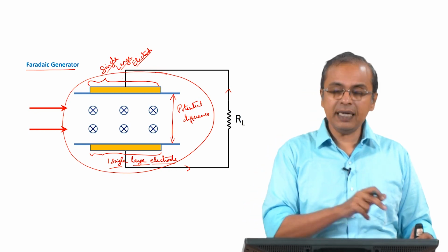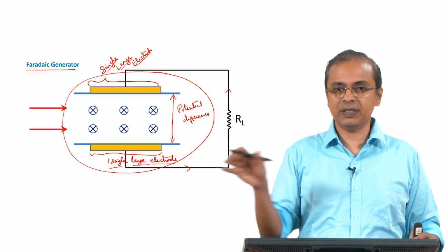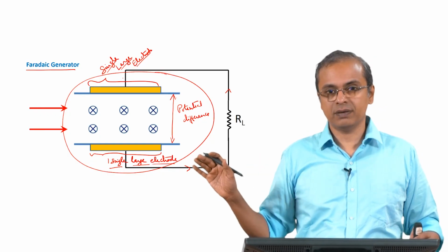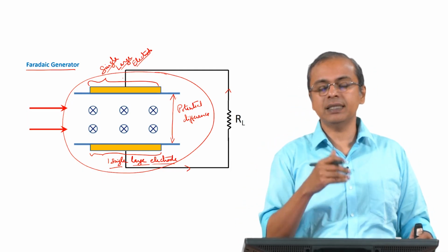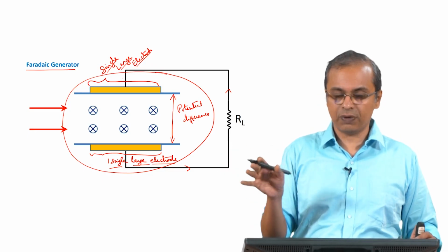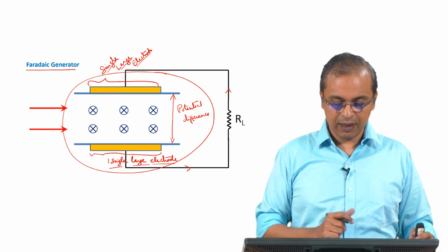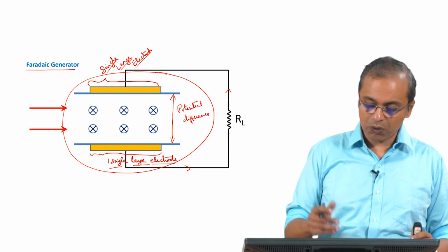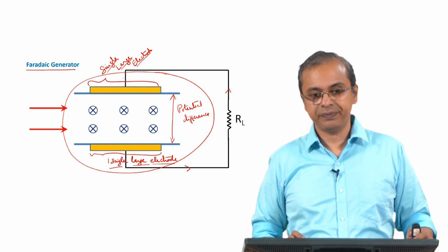So when you put a single large electrode, you are sort of smearing that out. Once you put a single metallic surface there, a single large electrode, you are essentially smearing out the Hall effect. So the difference in potential in the horizontal direction is being ignored, and it is being converted to one flat electrode of a common potential, and from that you are tapping the electricity. So that is what is happening when we do this single large electrode configuration, and there we are only looking at the effect that is in the perpendicular direction, and that is called the Faradaic generator.